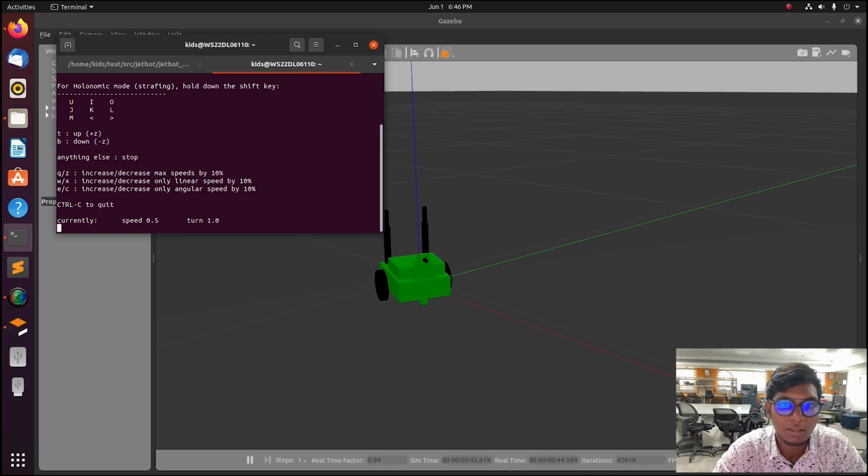It is working by publisher subscriber nodes, like our roscore is the master and the robot is a subscriber, and the teleoperate_keyboard.py node is a publisher. Using the cmd_vel topic, the node will communicate with the robot. After that, launch RViz.